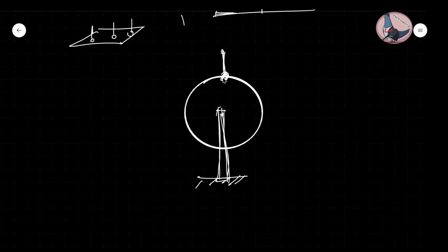We'll move the machine here, test it, take it to some other point, then come back, test the tip of this again, go back, and test it again, and we will take readings multiple number of times and see whether the same reading is repeating or not. If the same reading is coming 95% of the time, then we say, okay, fine, this is qualified.